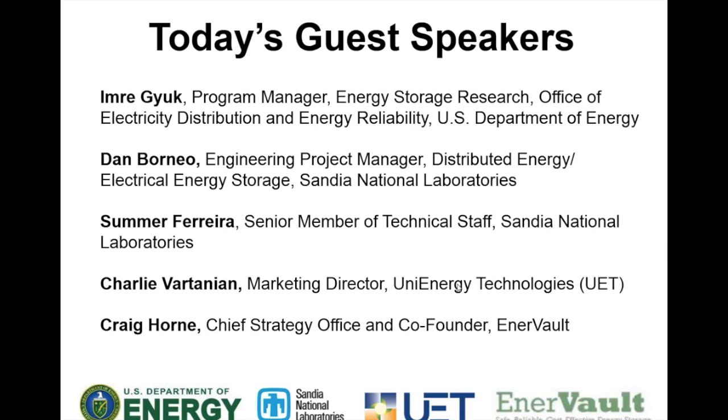Somebody wants to know if you could compare the efficiency of flow batteries, and would it be in the same range as compressed air, pump storage, or other bulk storage systems? I think in general, most of these systems are fairly similar in efficiency. Now, there are certain systems like flywheel systems that reach higher efficiencies. That's because flywheels are magnetically levitated and turning in vacuum. But the 70 to 80 percent efficiency is fairly universal among all different battery types.